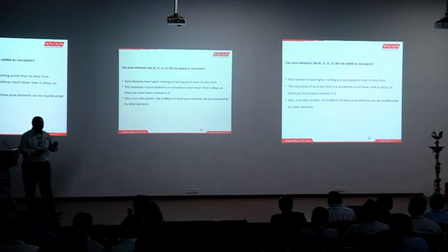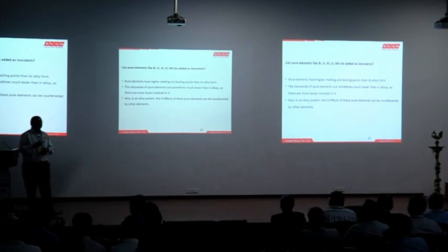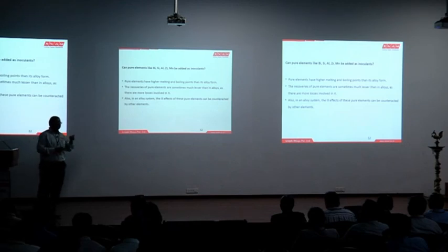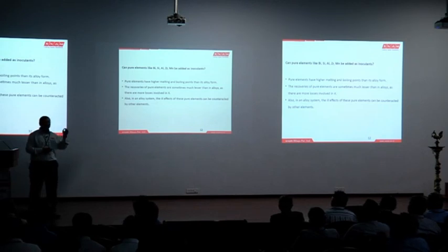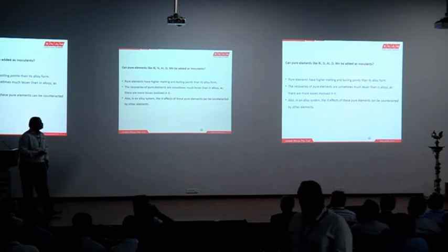See for example bismuth, or in ductile iron production there is an element called magnesium, the most important element being used. Magnesium is basically a carbide promoter. So the moment you add magnesium, it kills the metal completely at whatever level. Say 0.4, 0.2, 0.3, 0.8 or even 0.1, it kills the metal completely. So that is the reason why there is a demand for high inoculation levels in ductile iron foundries when compared to grey cast iron foundries. It is because the element magnesium is added. We cannot run the foundry without magnesium or an element closer to magnesium like cerium, lanthanum.